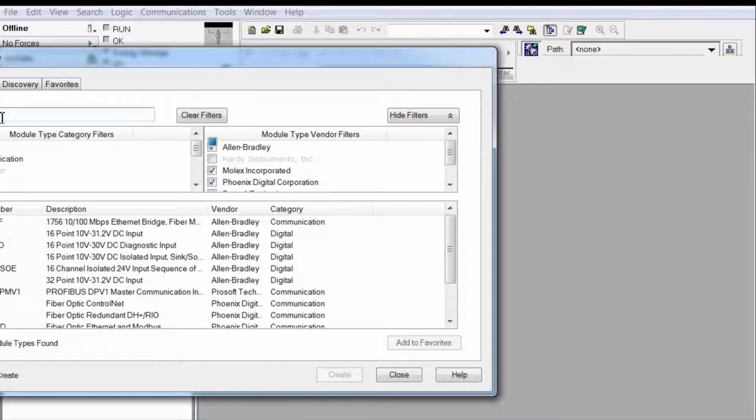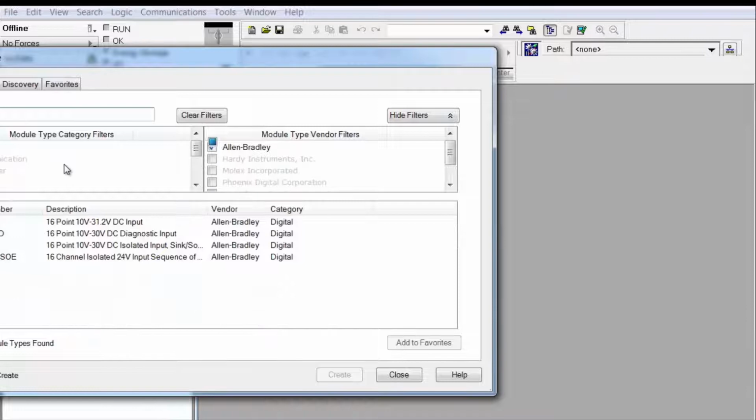See, they got rid of quite a few things. And notice that the check marks change too. So we go to 1, bang, see, nothing but digital left. Of course, putting in a 16 isn't going to change anything. So IB1 brings up what we want, IB16D. So you see there are 4 versions of the IB16. This is the standard module, the least expensive one. This one's more expensive. Now this is isolated, which is going to be more expensive than the standard, but I don't know how it stacks up price-wise with Diagnostic.